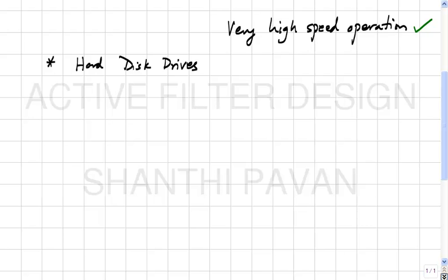So for all practical purposes, these are considered low frequency filters because the bandwidths are just of the order of several tens of megahertz. There are other wireless standards, for example, WCDMA, and these need filters with bandwidths of 1 megahertz, 2 megahertz, that kind of thing, right, all baseband stuff. But these applications, especially wireless applications, typically will require filter linearities which are very, very high. The reason why they require filters with high linearity is the following.